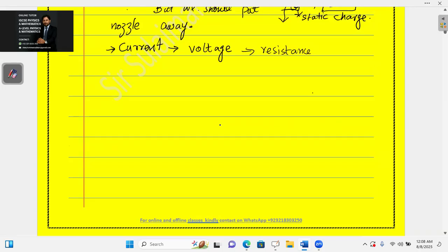An ohmmeter is a device that can also be used, but we use current-voltage graphs and take their gradient. In standard test circuits, we also used an ammeter in series and a voltmeter in parallel across the resistor with the battery, and we used their measurements for our IV graph values. We also checked AC and DC current. In AC, the direction changes at every moment, and in DC there is only one direction and the current is provided directly to DC appliances. Then we checked graphs for a constant-temperature straight line, for a wire, a resistor, a filament lamp, and a diode.